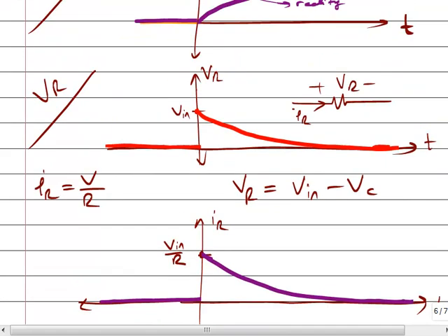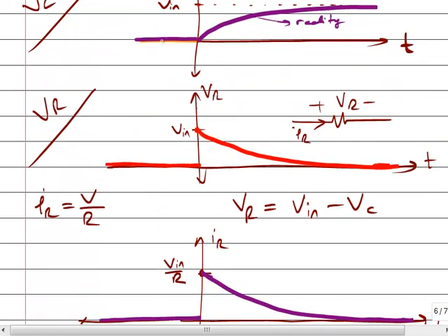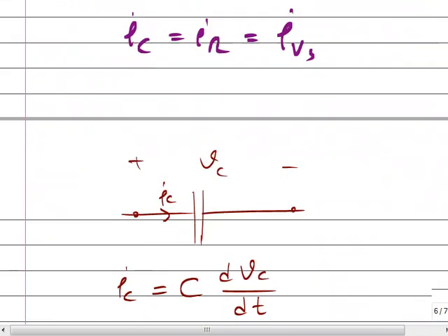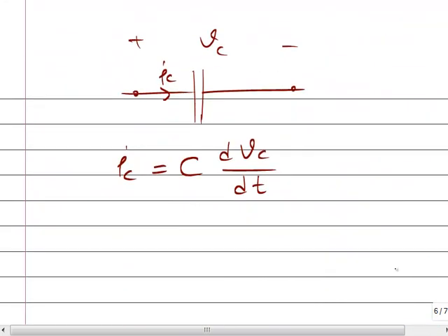Okay, as you see, when the voltage is 0, current is 0. When the voltage is some value but there is no slope, current is again 0. When the slope is high, current is high. As slope decreases, current decreases. So the current of the capacitor is dependent on the slope of the voltage. So the derivative gives the slope.